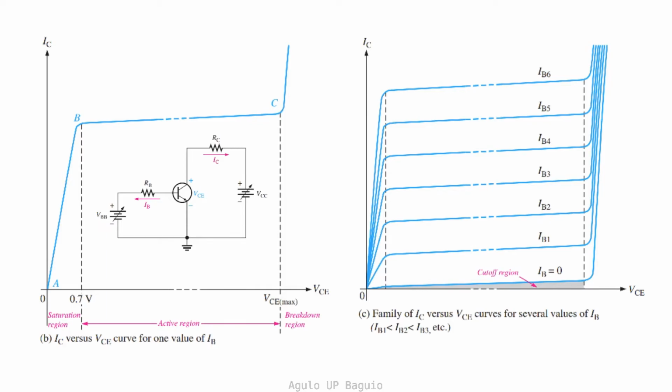As VCC increases, the current IC increases and therefore the voltage VRC. Since there is no base current, VCC is ideally all dropped across the transistor. There is still a small amount of current through VCE because of the resistance through the tunnel barriers, which thins out as VCC is increased. This is why IC has a slowly increasing trend with VCE.